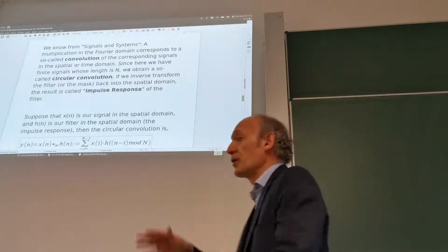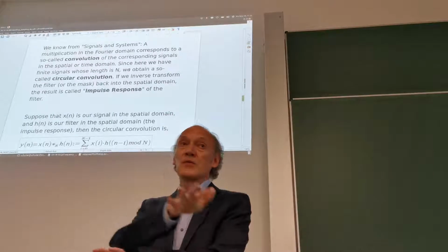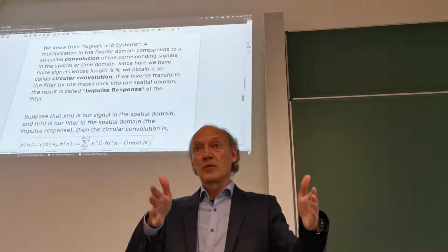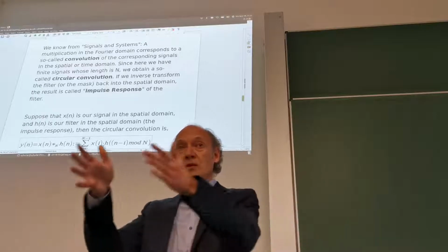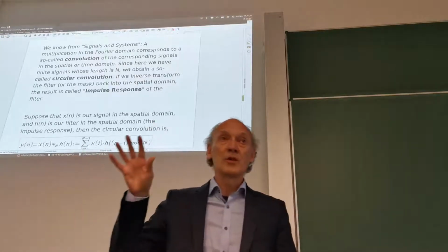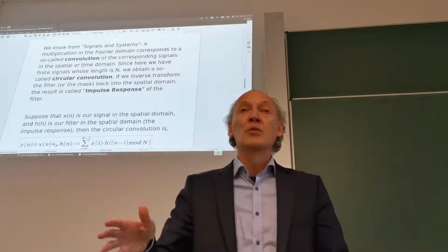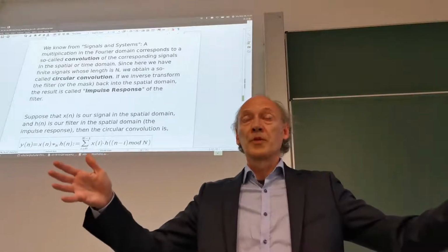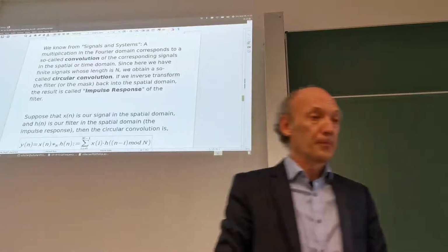The same is true for the inverse DFT. When we have the inverse DFT, we get a signal piece, but we have to think about the signal piece as one period. It would actually continue. And if you do multiplication in the frequency domain, you would have a convolution with this periodic continued signal in time or space.